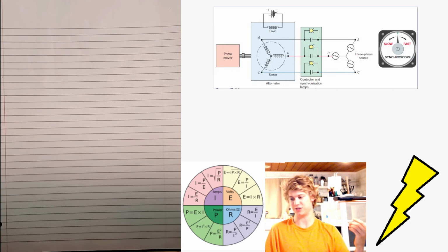The three-phase alternator contains three sets of stator coils positioned 120 degrees apart. The output from these coils is three separate voltages with the same frequency and magnitude. Okay, frequency and magnitude. What's not there is phase. And then it furthermore says, but they are 120 electrical degrees apart. So they're 120 electrical degrees out of phase of one another, because the phase is where it's occurring in time.